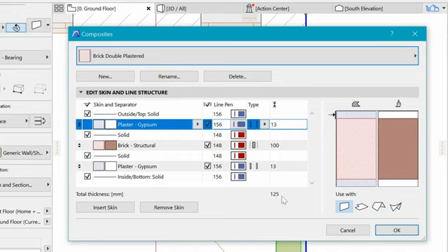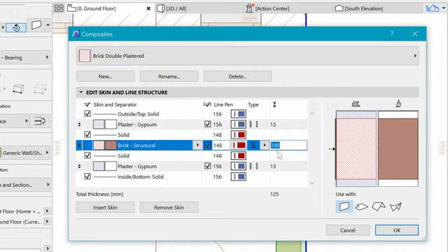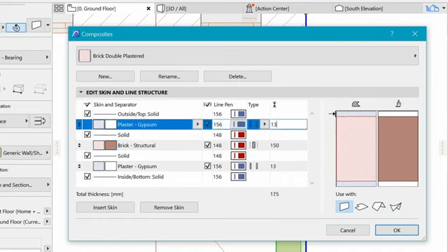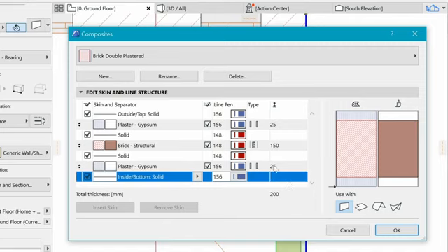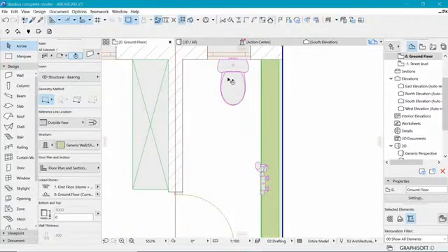are 200 millimeters thick. So I would like to increase this brick to make it 150, because I believe that's the thickness of a brick, and then we can increase the plaster to about 25 and 25, such that the total of it is going to give us a wall of 200. But then this is going to actually mess up what is already there by default. So that's why I think it is a bad idea to override what's existing.